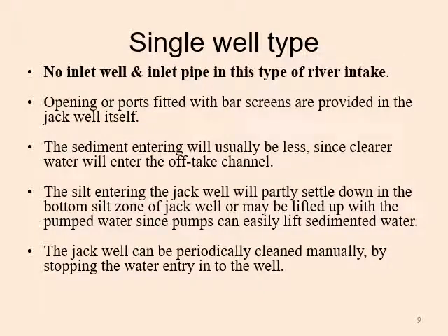The silt entering the jack well will partly settle down in the bottom silt zone of the jack well itself, or may be lifted up with the pumped waters. Pumps can easily lift the sedimented water. The jack well can be periodically cleaned manually by stopping the water entry into the well.